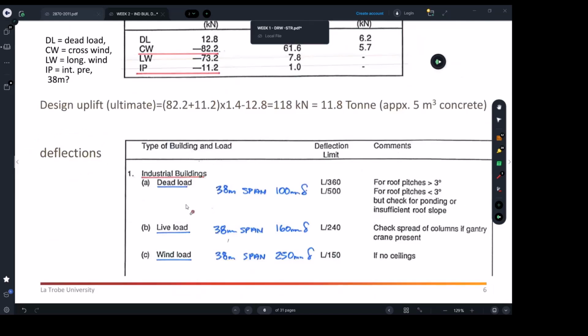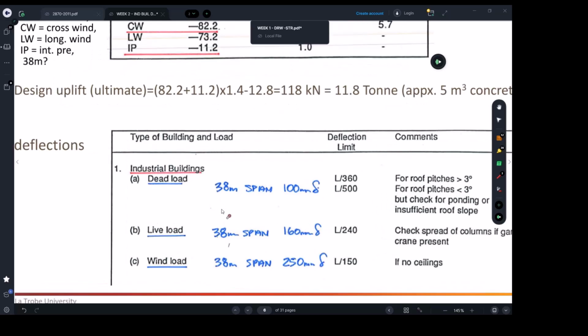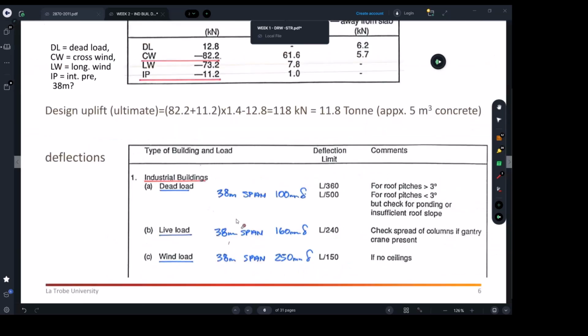Deflections, as I said to you, the engineers will be calculating. The engineer, by the way, as we're going to see in your assignment one project, may give you an idea of what you should expect to see after you actually build it. So you need to make sure this is what happened. Don't say it's not my job, because there may be a lot of wind blowing and over-deflecting. You are the first contact person, I don't want to say to blame, but to investigate the problem.